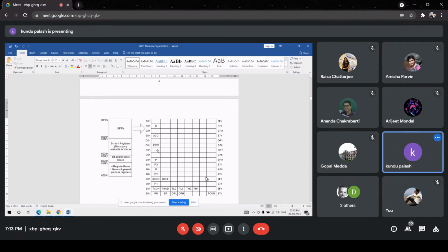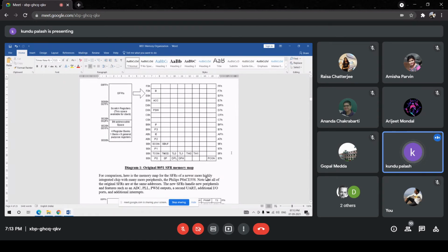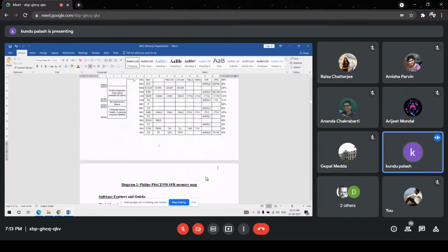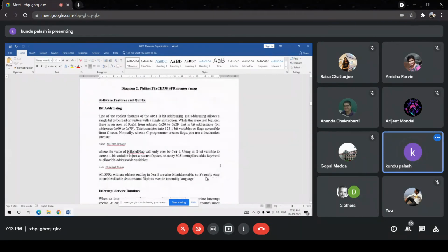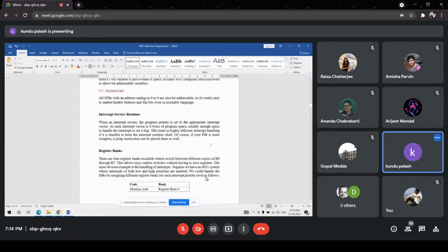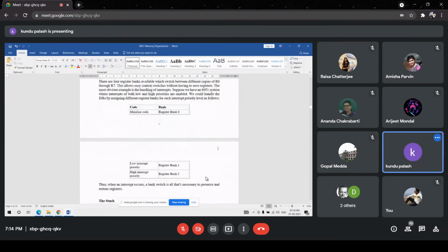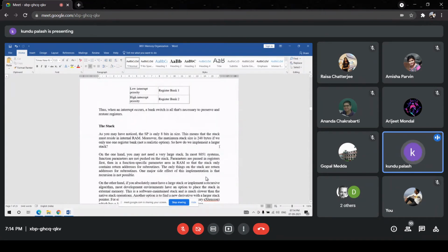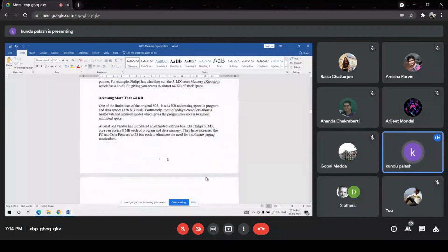So the nomenclature is P0.0, P0.1, up to P0.7. Whenever a symbol like P0.0 or P0.1 appears in a statement, it refers to bit addressing. That is the description of bit addressable. This is the software, or instruction, part. Right now we cannot fully understand until the instructions are taught.